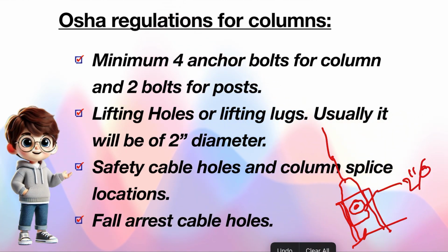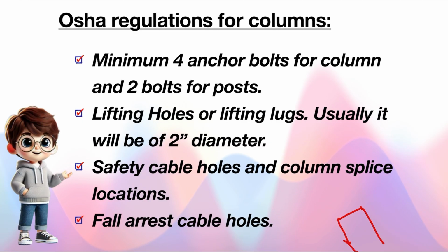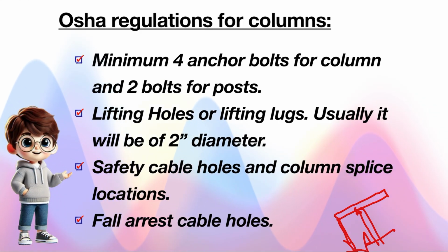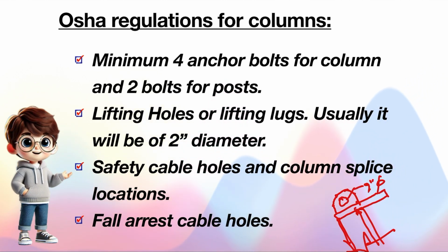There are 2 conditions where they use lifting lugs. For example, this is my column and there will be a moment connection or something, so I need a cap plate on my column. In this condition, if I need to provide lifting holes, I will add one more plate with a 2-inch diameter hole in it. This plate I call a lifting lug.